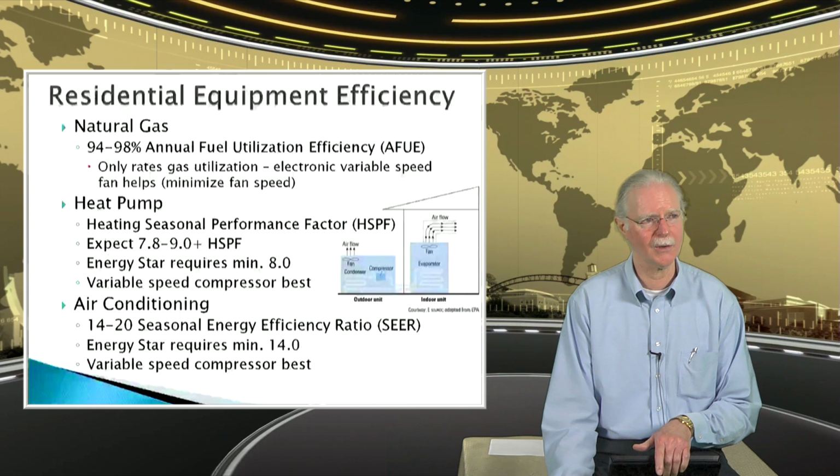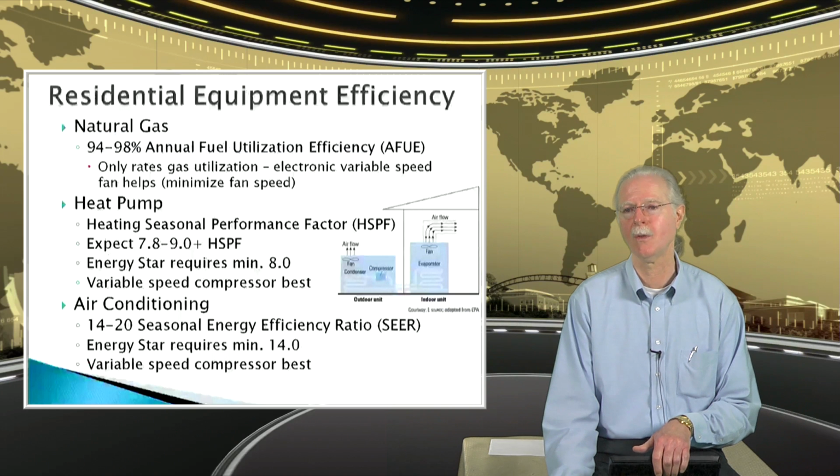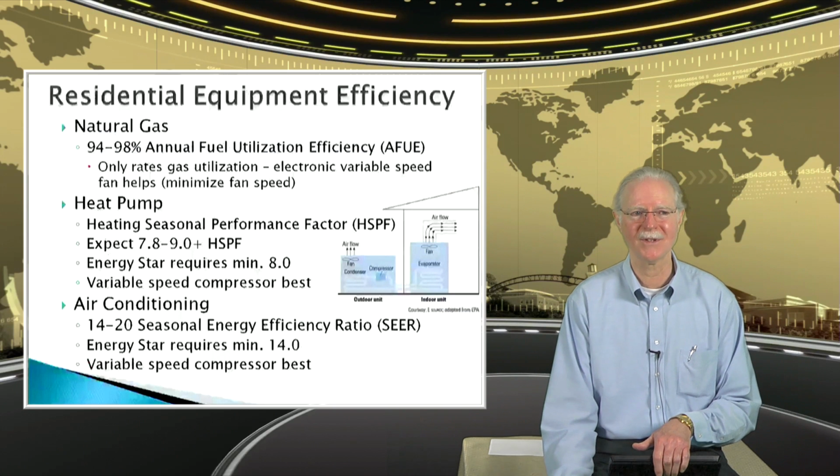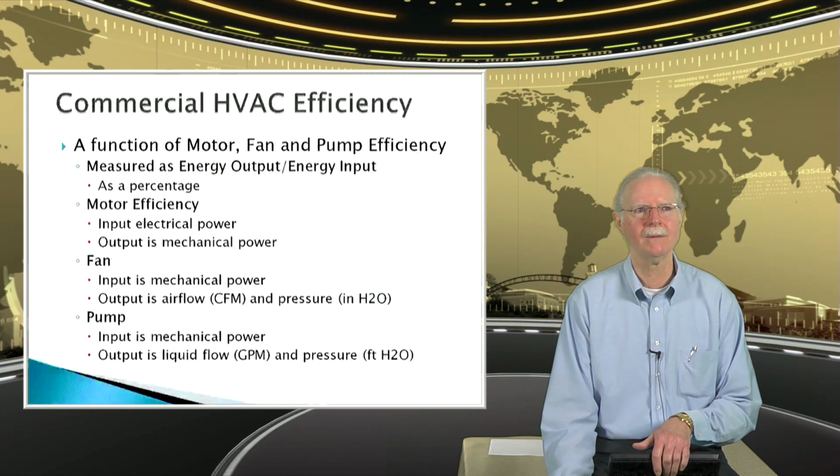So the current trend is to create compressors that operate at multiple speeds so that they're not operating at full capacity when partial capacity is all that's required. So those are choices. Now obviously when we look at all of these changes, if you want more efficiency, it costs more up front. And part of the decision-making process is how much do we spend? Is it worth the trouble?